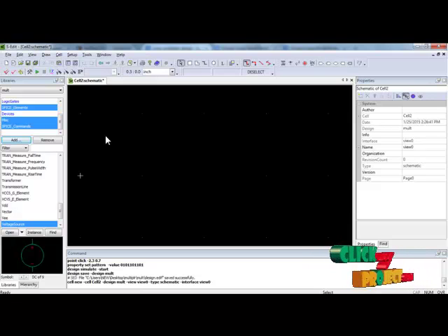In this we are using SEdit for circuit designing. After we design it, while simulating, the circuit's design will pass through T-Spice, which we can understand through the netlist generated as SPICE code. Finally, while we are simulating, the timing diagrams will appear in WEdit. Hence, commonly for our CMOS based designs, we will mostly use these edit tools, again I will say SEdit, LEdit, WEdit and T-Spice.